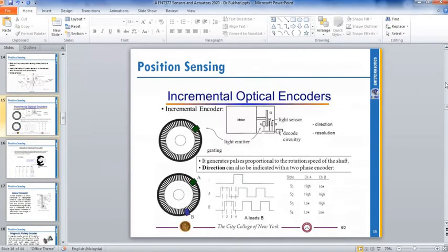The difference with this incremental encoder is that if you turn off your robot, you don't know your position, because this encoder is not absolute. It doesn't have a spatial mark to identify your robot or joint arm position. After you turn off your robot and turn it on back, your reading will be 0. So your counter also will be 0, unless you have